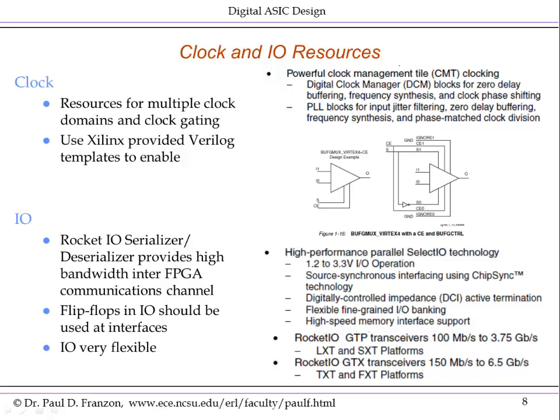FPGAs also have configurable clocks and I/O resources. An example at the top here, again, Xilinx family, they have programmable clock trees. You can not only set the frequencies, but you can do clock gating, you can do other things like that. And again, to make this easy to use, the FPGA vendor provides Verilog templates that enables you to use them.